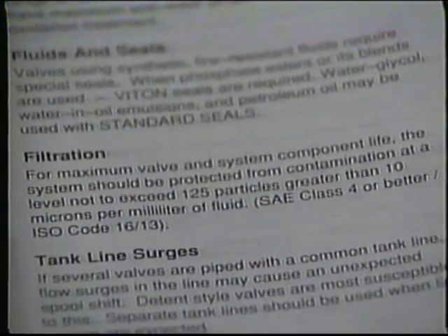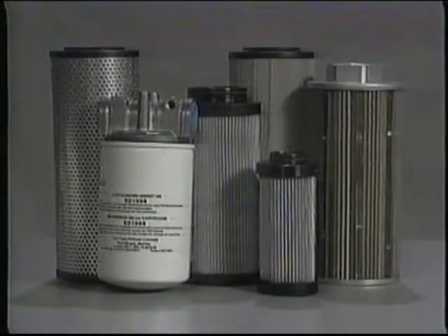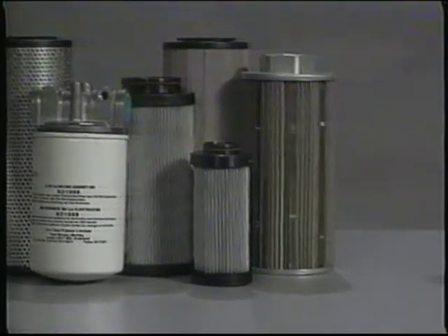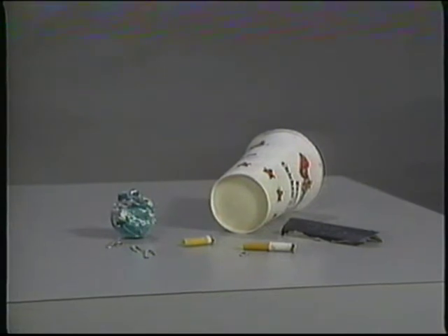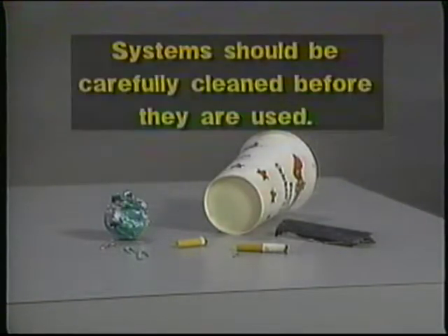To determine the kind of filter and the rating needed to protect the components of a system, you should check with the manufacturer of that component or with a reputable filter manufacturer. Filters remove dirt from a hydraulic fluid, but there's a lot you can do to keep dirt out of the system in the first place. Paper cups, cigarette butts, metal chips, emery paper, rust, paint, all of these have been found in the reservoirs of new systems, so all systems should be carefully cleaned out before they are used for the first time.